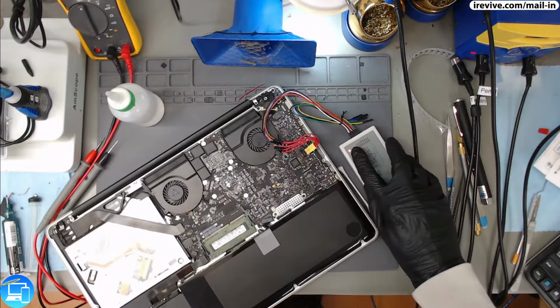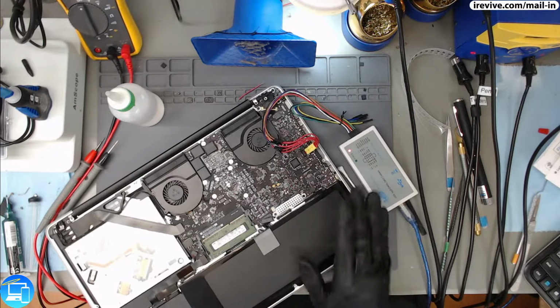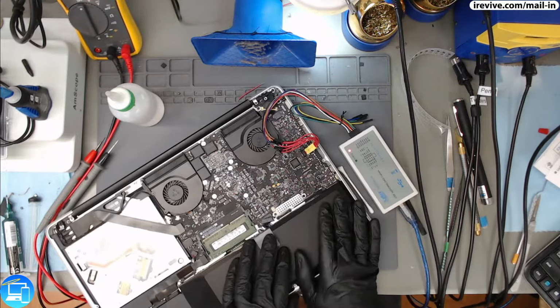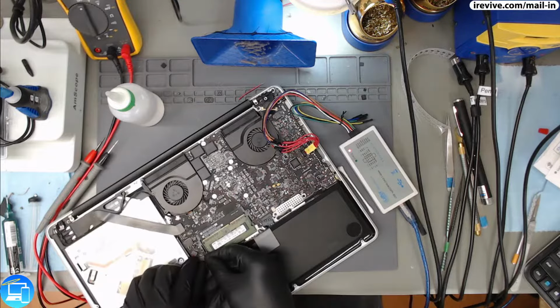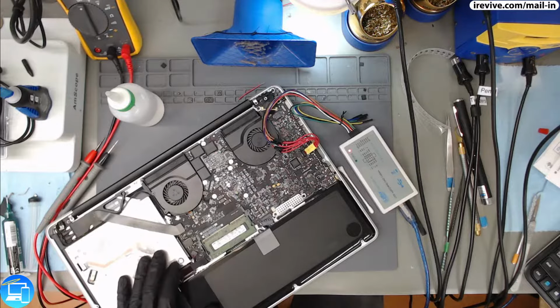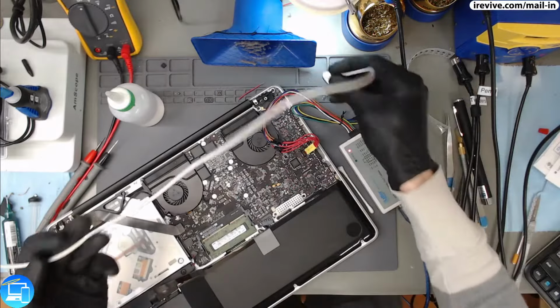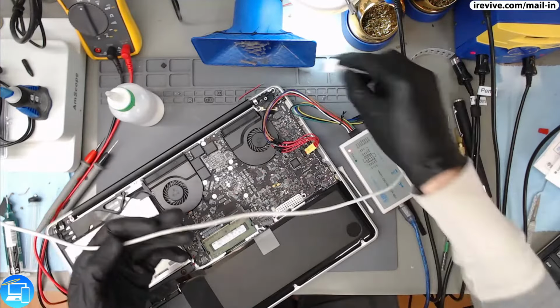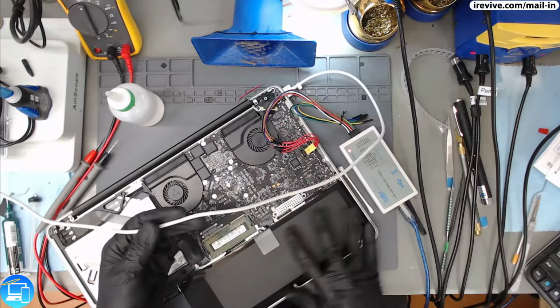And now we have a red light, and when it's ready to be programmed, it's going to turn into a green light. So before we actually begin the programming, we want to make sure our battery is disconnected, and just to make sure we're not corrupting data, we're going to unplug the hard drive or the solid state SATA cable from the logic board. Then, after that, we are going to get an 85-watt MagSafe 1 adapter. It has to be 85 watt. A 60 watt will not power the board with the battery unplugged. It would require the battery.